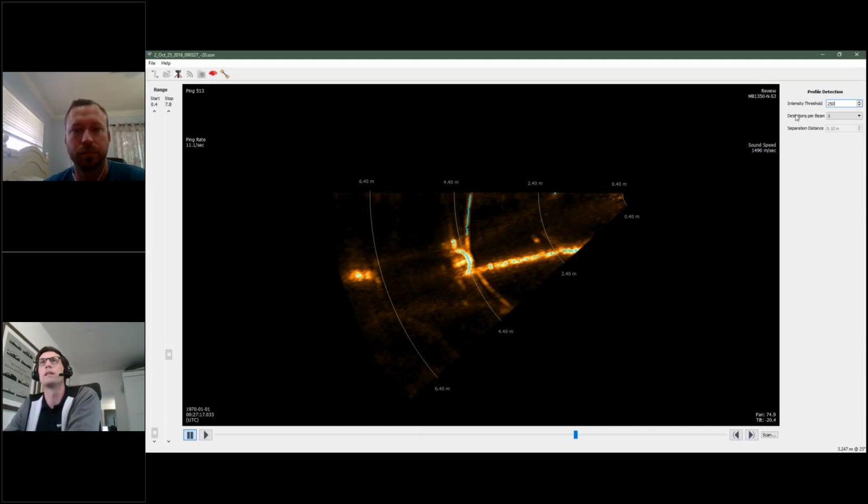So yeah. The other setting here is Multidetect. One thing I'll say about this is absolutely, generally under any circumstance, do not use this during acquisition. I found it really slows the computer down. So I would really only play around with this during playback. Same with the threshold, but this is even more important to do after the fact. So basically every one of the 256 beams of the sonar is going to pick the one strongest return along that beam. That's just the default setting.